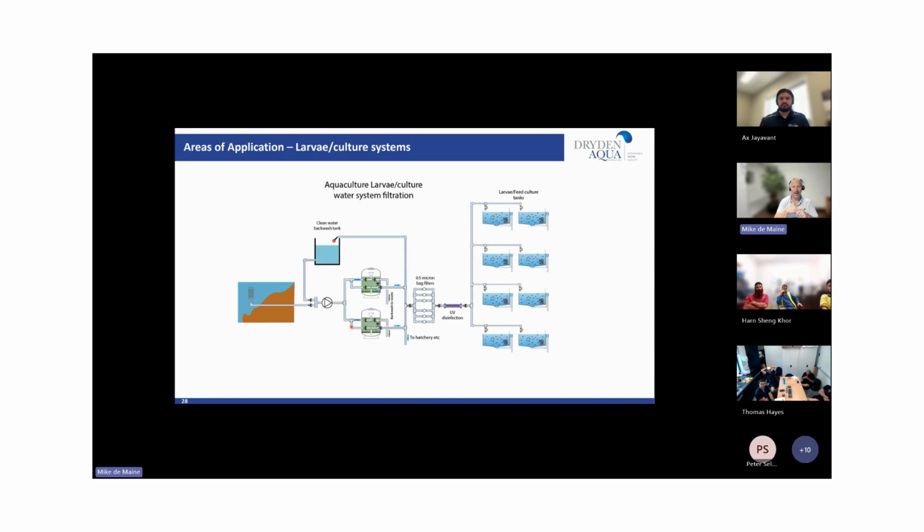So if you don't backwash those filters, what you'll see is over time, you'll start seeing fines penetrating, because there's no more surface area on our media to absorb the fine particles. So once the media surface in that whole filter has fully accumulated with fine particles, there's no more space for those fines to be removed, so they will start penetrating through the bed.